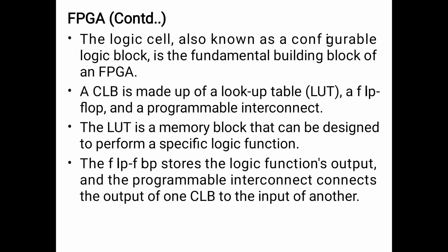The FPGA has a logic cell which is also known as configurable logic block. It is the fundamental building block of FPGA and it is made up of lookup table, flip-flop and programmable interconnect. The lookup table is a memory block that is designed to perform a specific logic function. The flip-flop stores the logic function's output and the programmable interconnect connects the output of each configurable logic block to the input of another one.